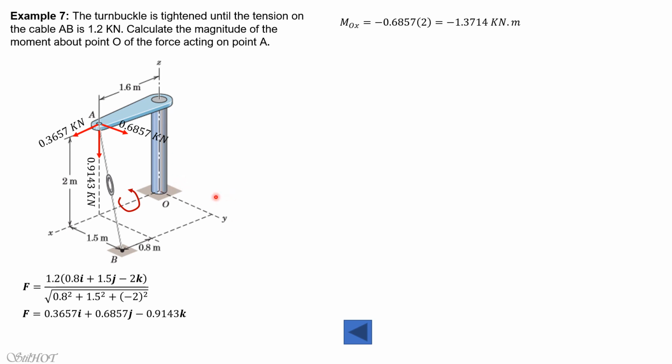Now, how about y? So position your right thumb towards the y-axis, then the positive moment would be the same as shown in the figure. So let's ignore the y component. Let's concentrate only with these two forces, the x component and the z component. For the x component, it is same sense as this, so it is the same curling.